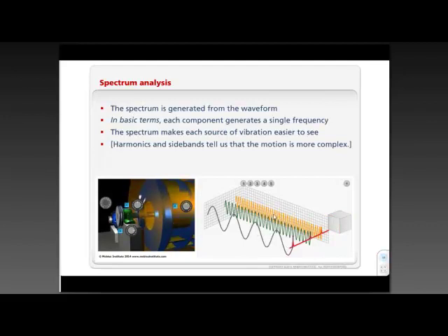Here are our 3 sources of vibration, but they are separated according to their frequency. Low frequency is the grey one. Higher frequency, in this instance, is the green one from the bearings. And because we have so many blades on this fan, it's an even higher still frequency from the fan. That's that orange vibration.